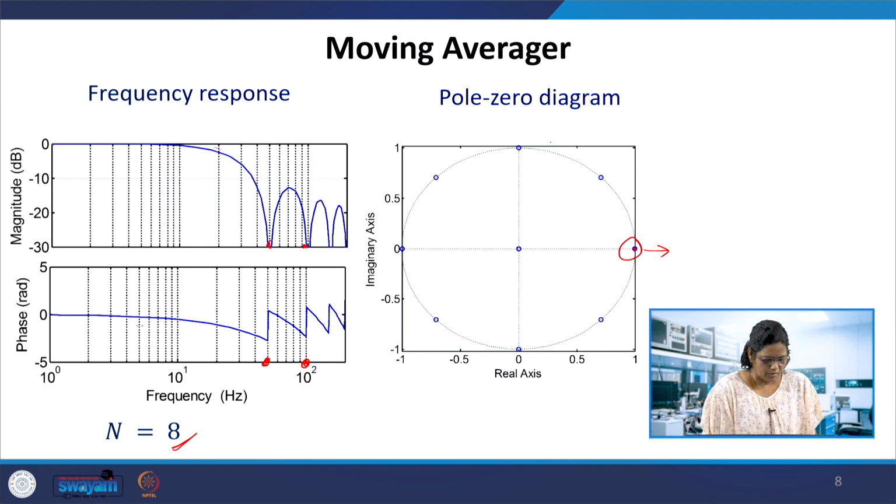The phase shift here is 0 radians, so there is no phase shift introduced for these particular frequencies. So it can be tuned to get only DC. DC is perfect here, giving 1, and it's not plotted from 0 on the log scale. So DC can be extracted using the moving averager, which just averages the number of samples.